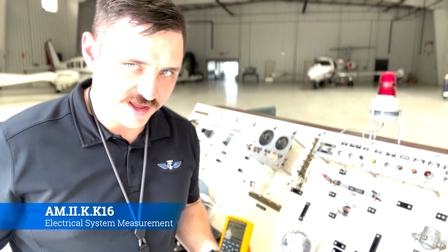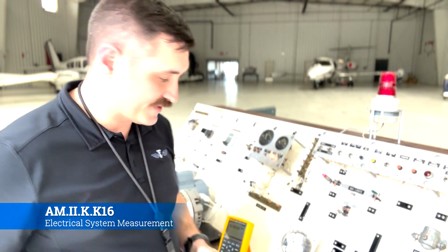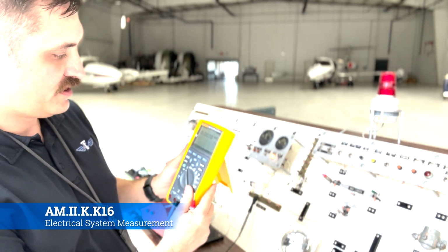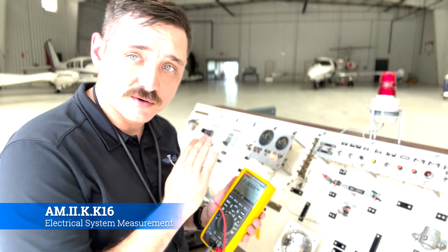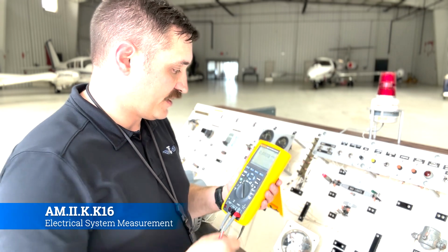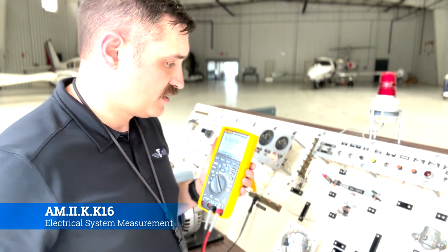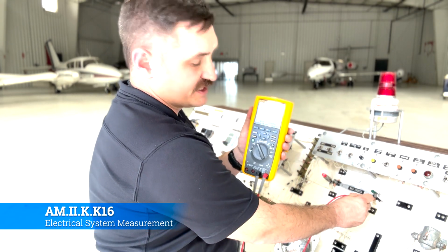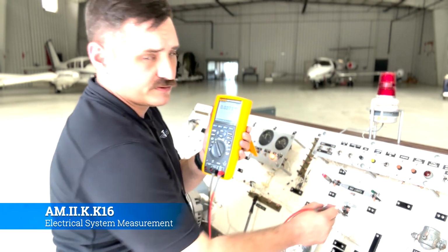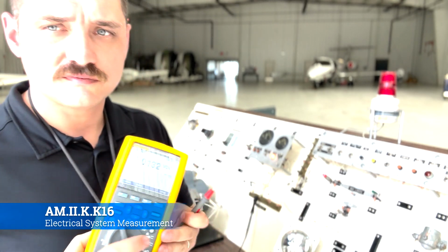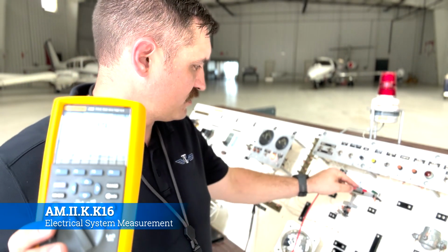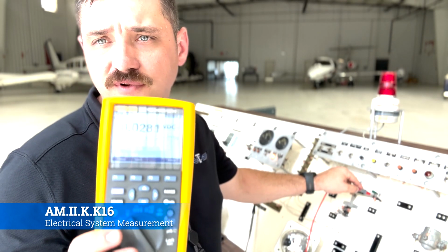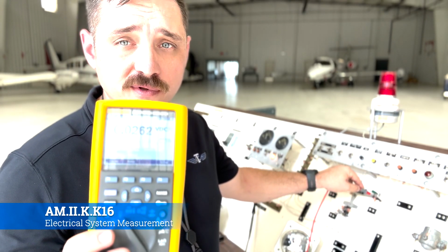First off, let's just see if we have power going there. So we're going to need to go to a ground. So we have a ground bus right here. We're set up on DC voltage because we don't have AC going, it's just DC volts. Turn the light on, maybe you can see it a little bit better. All right, and we're just going to pin right there at the junction. We see that we have no power going to it. You can see that there's no power going to that light bulb, so that we have a power problem.